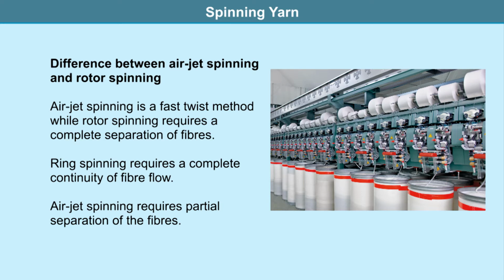If only the twisting nozzle is working, this will result in pure false twisting of the fibers and forming a yarn. However, when the yarn leaves the nozzle, untwisting takes place. In the actual machine, the two nozzles apply air rotation in two opposite directions, with one nozzle imparting a higher rotational speed, avoiding complete false twisting. The resulting twist is the difference of the two imparted twists.